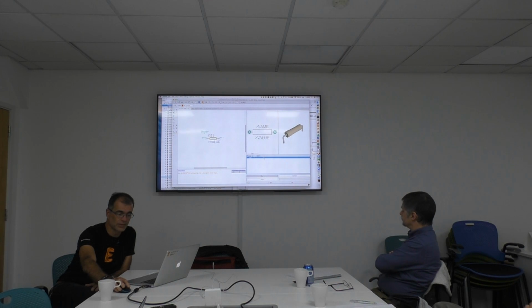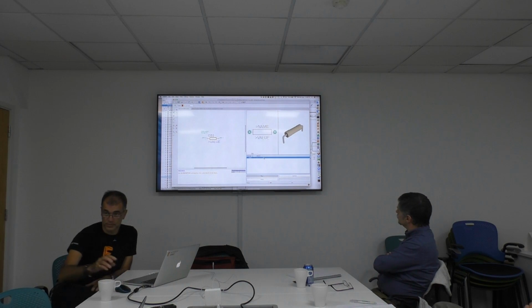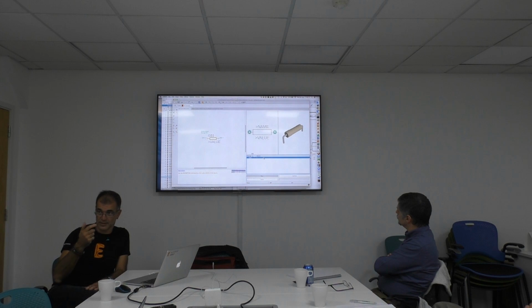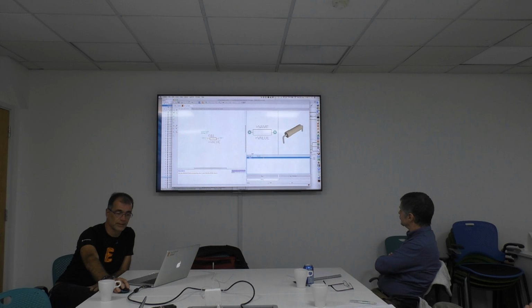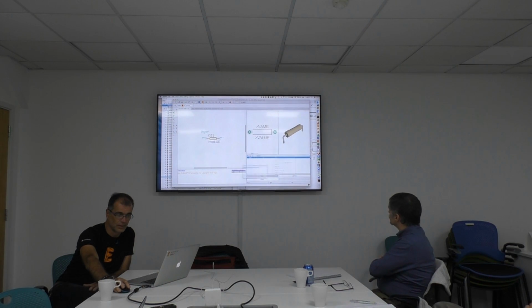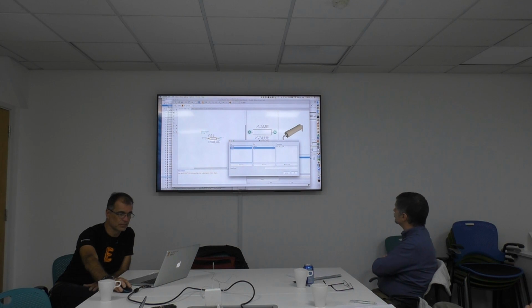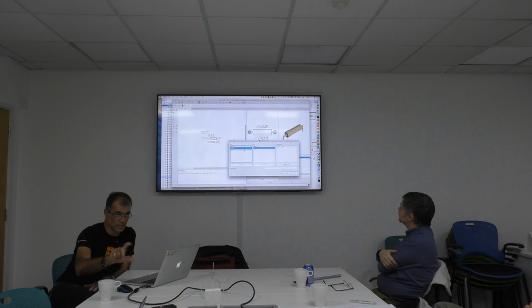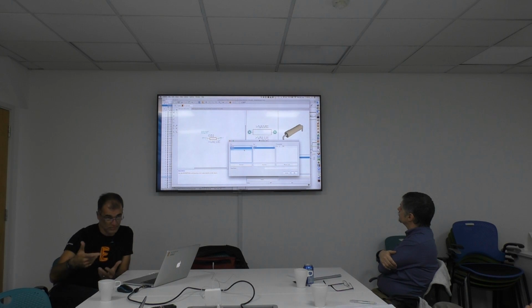So, and then you see this small sign. This means we have not yet assigned pins and pads. And that's what I'm doing basically here, or maybe even with the right click, I can use Connect. Then I get a list. You see I have pins, that's pin 1 and 2. And they have pads 1 and 2. Here it's not critical how to assign, but if you have a more complex component, then of course you have to look at what belongs to what.